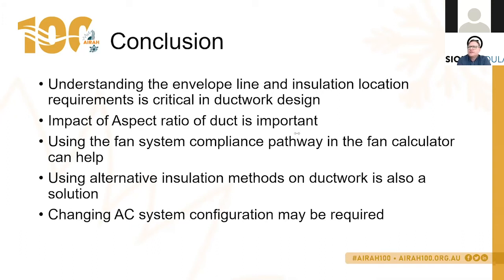Where is the insulation and the definition of the envelope line? In the majority of instances, particularly in high-rise buildings, the envelope line will be the external fabric from slab to slab. Therefore, the ceiling space that is within that envelope line ends up within the conditioned space.